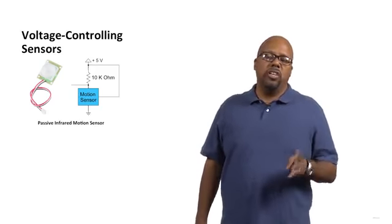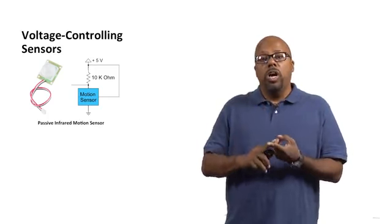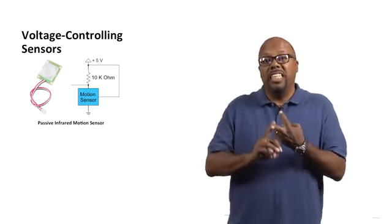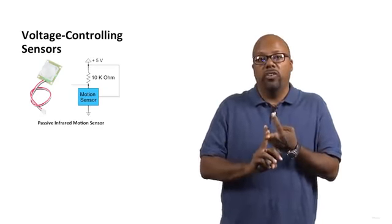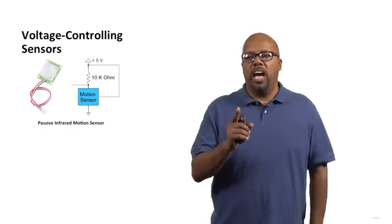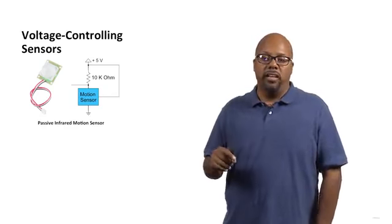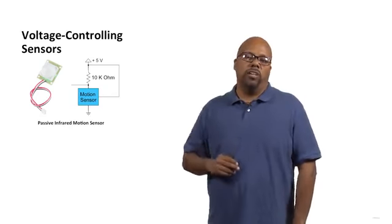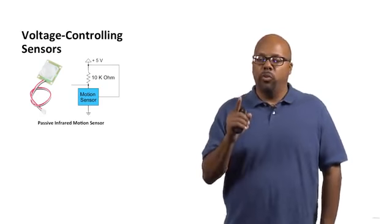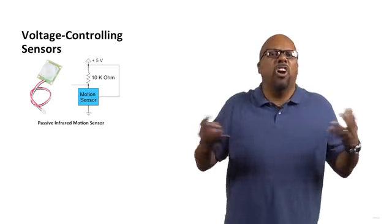A PIR motion sensor has 3 leads, 3 wires, 3 terminals, whatever you call them. One is connected to power, one is connected to ground, and one is the signal that you're interested in, the voltage that you're interested in. If we look at our motion sensor block over there, it has 1 pin on the top, 1 pin on the bottom, and 1 pin on the right side. The pin on the bottom is wired straight to ground. The pin on the right is wired straight to power. Okay. The pin on the top, if you follow it, goes to the left, which is presumably going to our Arduino, right?